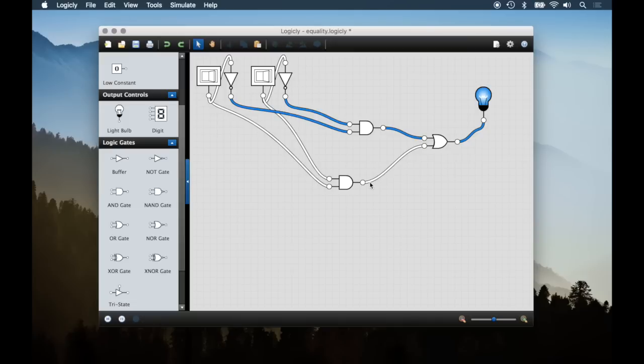Now, we talked about rails in lecture, that is drawing out the wires from both the input pins on the diagram and the NOT of the input pins. For example, something like this where you could draw the wires all the way down. But logically we can't do that because a wire actually has to end up somewhere for it to be on the diagram. So you can see it just appears when I let go of it. But this type of configuration more closely matches what you're used to. So although you can't make rails here, you can put the NOT gate next to the switch, and you can draw from both the NOT gate and the switch. Okay, so that's implementing a circuit using logic.